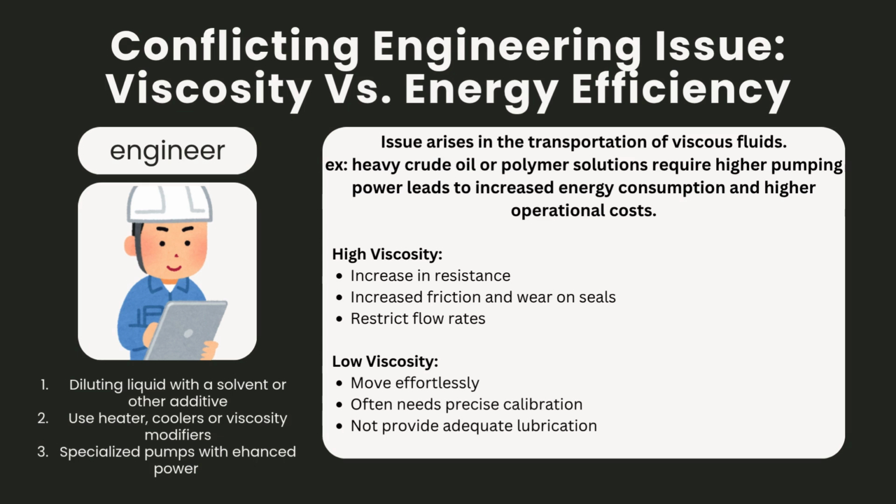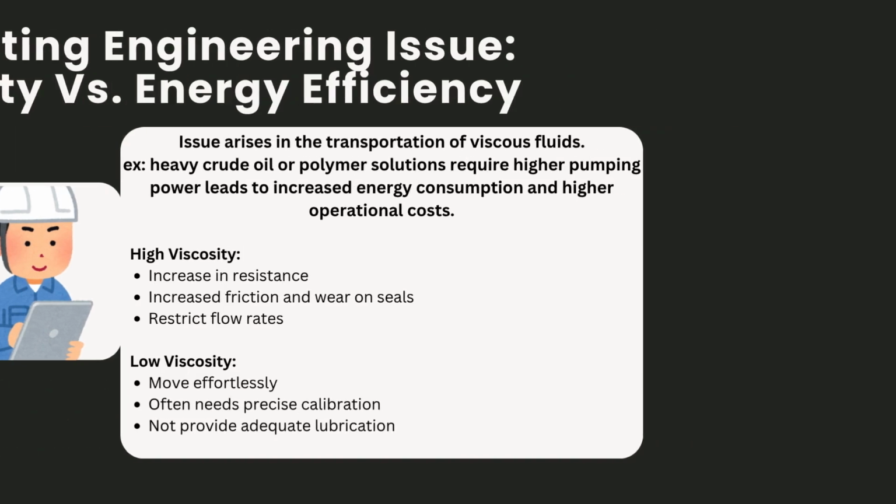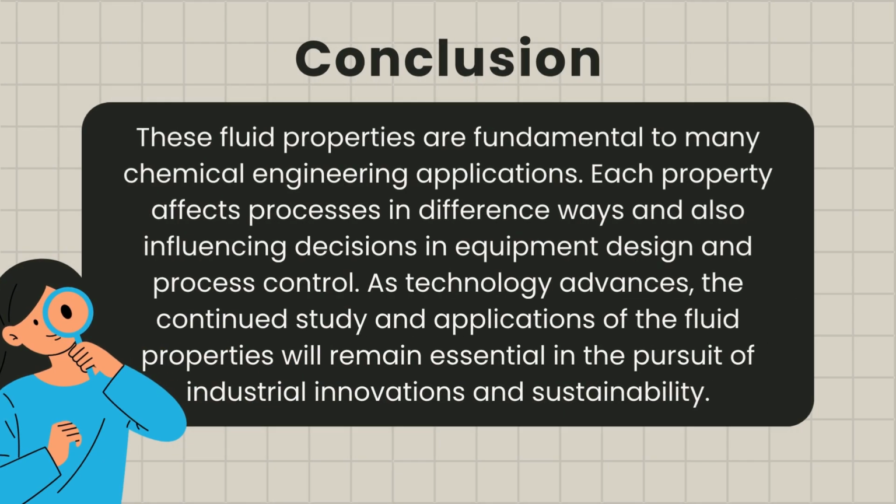Low viscosity fluids more effortlessly make transportation, pumping and other movement-related processes more efficient, but often need precise calibration to ensure optimal performance. Fluids with too low a viscosity may not provide adequate lubrication, so the engineers come up with some solutions, which are diluting the liquid with a solvent or other additive, the use of heaters, coolers or viscosity modifiers, and specialized pumps with enhanced power.